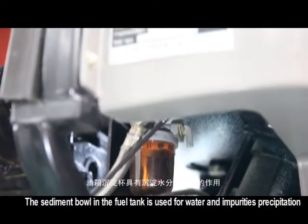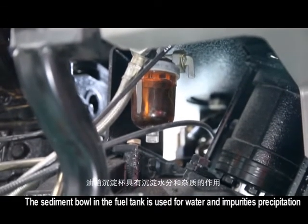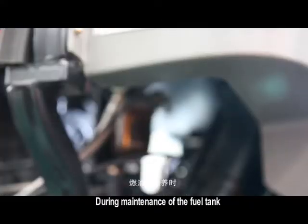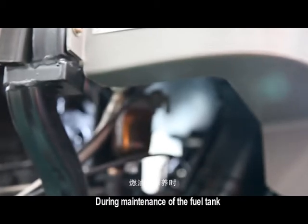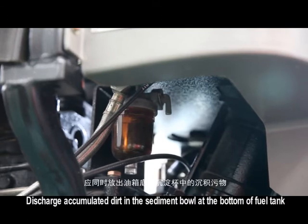The sediment bowl in the oil tank is used for water and impurities precipitation. During maintenance of the fuel tank, discharge accumulated dirt in the sediment bowl at the bottom of the fuel tank.